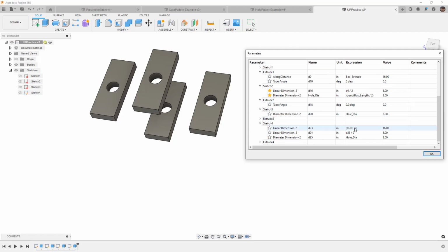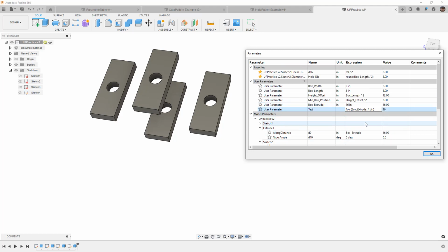If you really don't have a parameter that's driving that value and you need it for something, then think about ways in which you can restructure your design to get it. Or you can use that driven dimension and hopefully it won't cause you any problems in your formulas. But if you do, if you run into a problem where it doesn't seem to work, then go back and see if you can reformulate a parameter to drive that value.